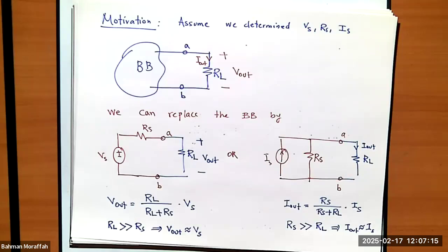If this V out is negligible, let's just say it's 0, what does it mean? It means there should be a wire there. Because I know V out in both circuits must be the same, right? So if in the current divider V out is 0, what does that tell me? It means it's a wire there, right? And therefore, all the current that I have is going to flow through that branch, right? So these two things actually match.